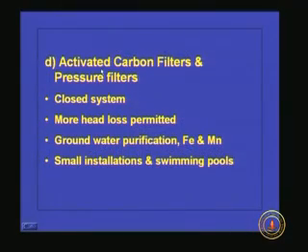So, depending upon the quality of raw water, we can decide which type of filter we have to use. It can remove even dissolved gases. Most of the time these filters are operated in a closed system and more head loss is permitted, because the filter is running under high pressure. So, it can take more head loss, and usually it is used for groundwater purification where Fe and Mn have to be removed, and this is used only in small installations like swimming pools or some industrial complexes, etc.